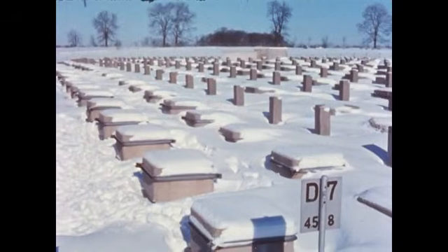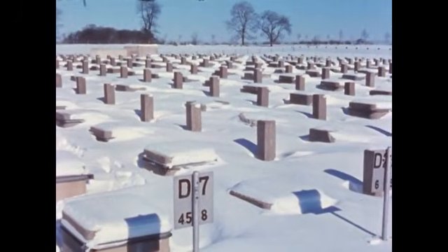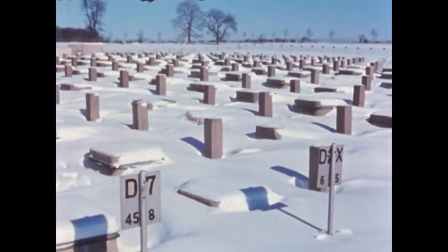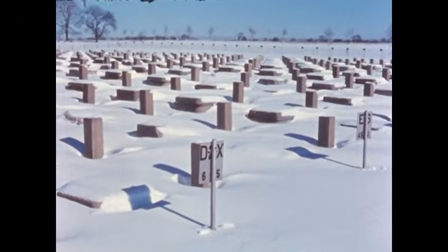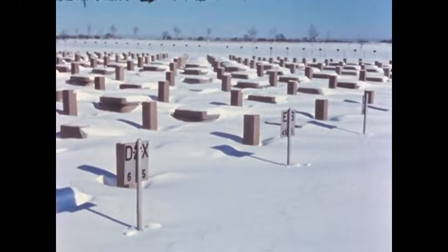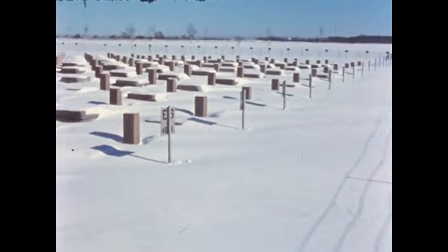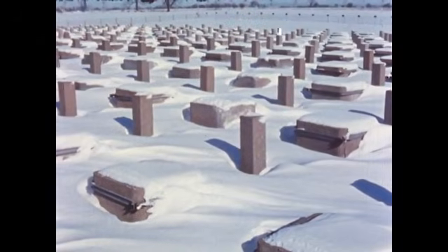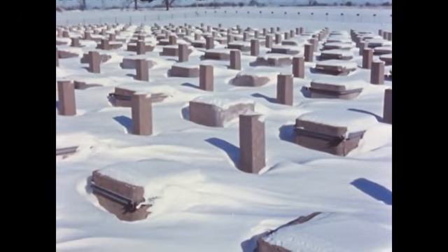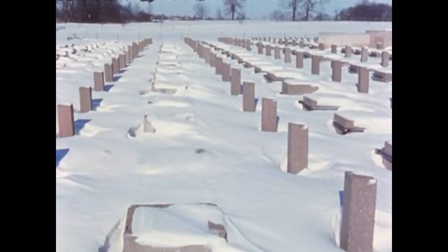To study the effects of natural weathering, the Portland Cement Association, in cooperation with various government agencies, built thousands of concrete specimens. These were subjected to snow, rain, sunshine, hail, and freezes from early 1941 until the conclusion of the test in 1966. Results of these studies, completed after 25 years of exposure, showed that intentionally entrained air in cement paste improves the durability of concrete.